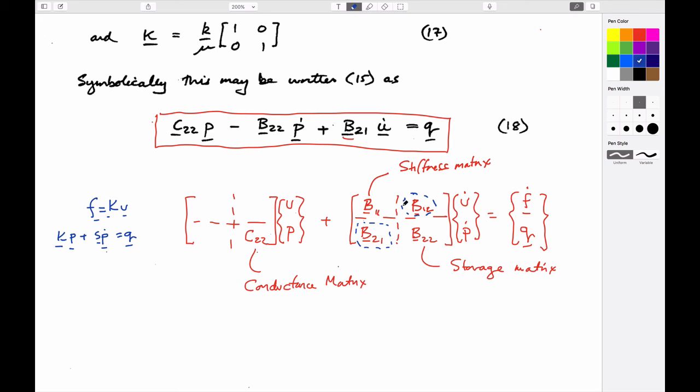And these ring terms are the coupling terms. And again, just to reiterate without doing it to death, this has to be in terms of volume flux. So this is a source, if you like. In the same way as we talked about the dual porosity systems, two overlapping media, one fractures, one matrix, they act completely independently of each other, but we allow them to talk to each other by this fluid exchange term. What goes out of one system has to come into the other system by continuity.